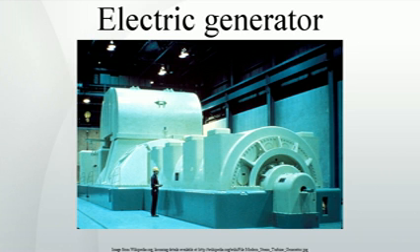When the generator first starts to turn, the small amount of remnant magnetism present in the iron core provides a magnetic field to get it started, generating a small current in the armature. This flows through the field coils, creating a larger magnetic field which generates a larger armature current. This bootstrap process continues until the magnetic field in the core levels off due to saturation and the generator reaches a steady-state power output.